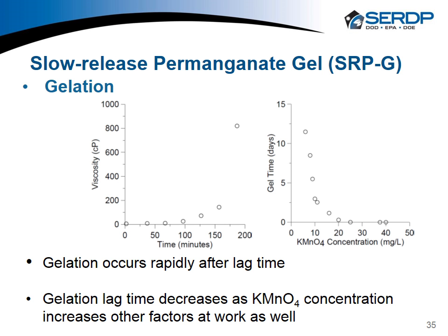As shown here, the viscosity stays sort of the same for, in this case, about 100 minutes, and then it picks up and starts increasing rapidly over a very short period of time. So that was the typical pattern that we see when gelation occurs. It doesn't change for a while and then rapidly increases, rather than gradually or linearly increasing with time.